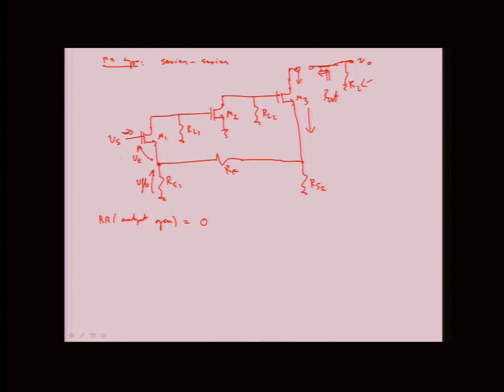So you're doing the signal processing on this loop over here, right? But we know that at the input, if you're doing it in a loop, you're really processing voltages, right? But you're sensing, in a loop, you're sensing current, right? That's this loop over here. Okay, so I just want to make sure that this doesn't confuse you, because as apparently it does, right? But it's a very critical thing to see that you don't get the loading confused with where the feedback is. Okay.